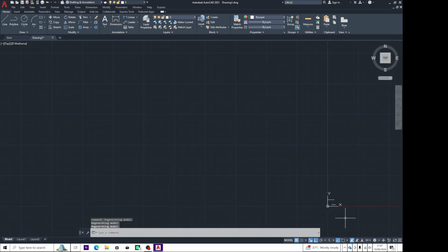Then another toolbar we shall be looking at is right here, down here, from here up to this far end. That toolbar is called the status bar. The status bar is comprised of the model or paper space, which is these two. Then you have the display, your snap mode, your dynamic input, your ortho mode, and very many. I may not read all of them.